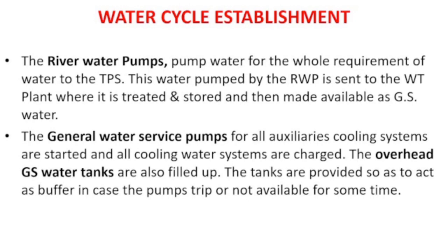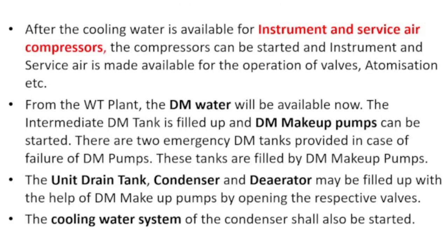The tanks are provided so as to act as buffer in case the pumps trip or are not available for some time. After the cooling water is available for the instrument air and service air compressors, the compressors can be started and instrument and service air is made available for the operation of valves, automation, etc.